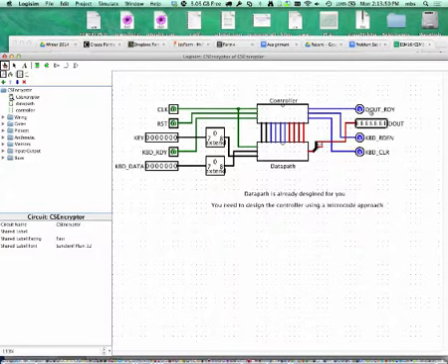Yeah. Is ROM a type of register? ROM, you can think of as a whole bunch of registers plus some decoder for the address lines. So if I had a bunch of registers and I put a decoder in front so that I enable one, and a multiplexer so that I read one of the registers out, that's essentially what a ROM is. It's implemented differently because it conceptually can be a whole bunch of registers, so you don't design it as registers. Any other questions?